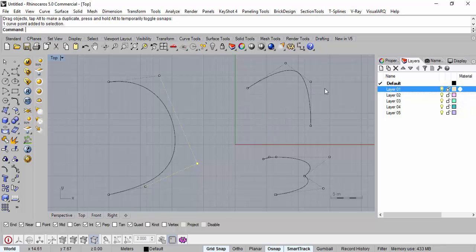This one you're saying, the arc, the same one. How I added control points. Very simple. You select this line. You want to come out of this control points mode. You can just use function F10, or you can just click on this again. No, it doesn't work. Or use escape twice.